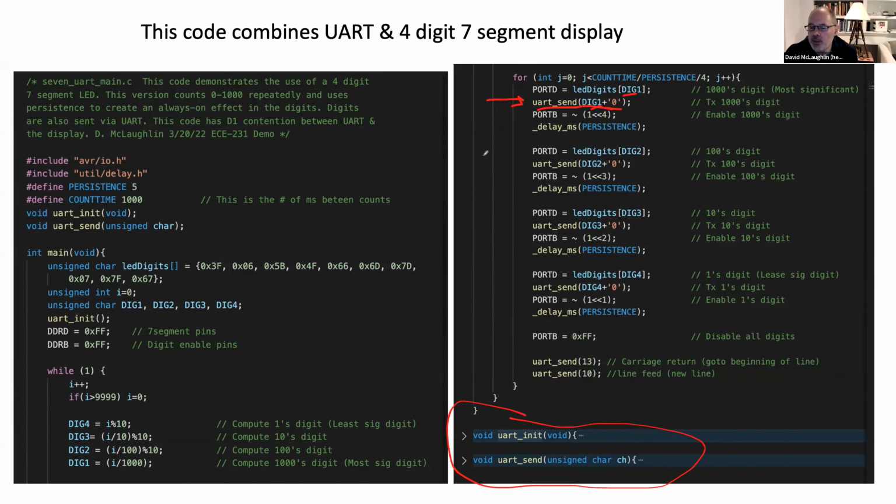It does require that you get into some bit twiddling here, because what you want to do is write to port D with a full byte. And here we're going to have to take away one of the bits of that. And so I find it convenient when you can, if you can't work with a whole byte, work with 2 nibbles, right? 2 4-bit chunks, because each one conveniently corresponds to 1 hex digit. So what I'm going to do here is I'll go back to the previous slide, and we were using all of port D to control the segments of the LED, and we were using port B here, for the enable pins for those common cathodes.